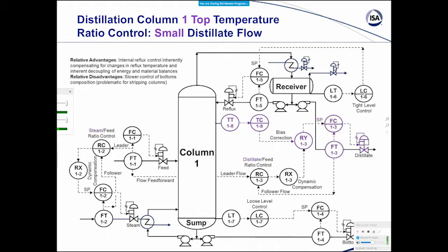radar, something like that. Anyway, tight level control, which then says, oh, the level changed, so the distillate flow changes, because the temperature controller wants to affect the column, and it does that by way of the reflux flow. I'll do my job. The level controller says I'll change the reflux flow. Now, you can use feed forward from distillate to reflux to make that happen sooner. But you still need tight level control, because there is an internal reflux control that is being done here.